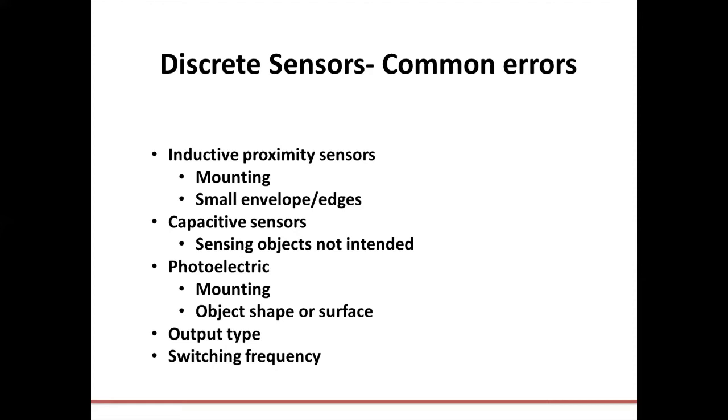Photoelectric sensors: there are many specialty types of sensors which can detect things like transparent bottles, labels, and odd surfaces. You want to make sure that reflective objects are not used with photoelectric sensors as well, because they can trigger a false count. Angled packages can also trigger false counts and false detection. You want to make sure that you choose the proper output type.